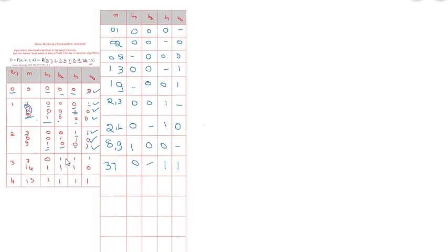Now we will go with 3 and 14. But what happens with 3 and 14? In 3, B1 B0 are 1, but in 14, B1 B0 is different. So it is not possible. Okay. Then we will go with the 6. In 6, B2 B1 are present, and B2 B1 are present in 7 also. So we will do the grouping of 6 and 7. In 6, 7 the last bit is the only difference, 0 in 6 and 1 in 7. So 0 1 1 is equal and the last bit differs.